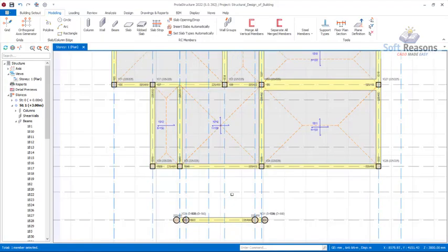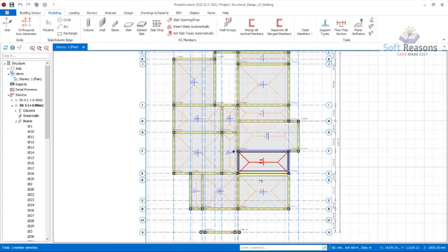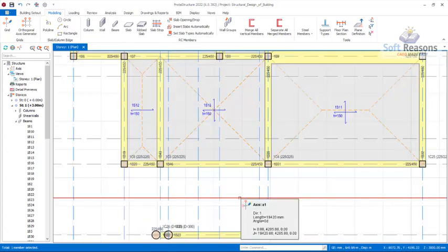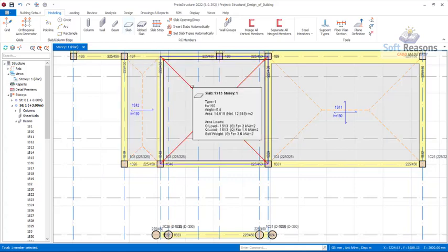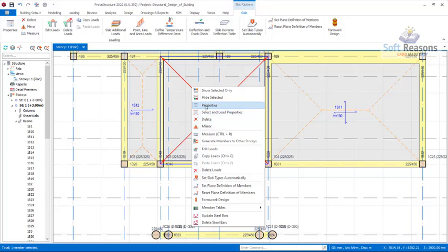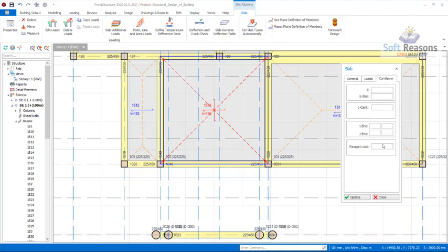So we proceed. Having placed the reinforced concrete slab successfully for this cantilever slab, because this is the first floor, you can see at height 3 meters. So we need to place a cantilever slab. You can use the property of this slab, then come over to the provisions and change it to slab type 12. After which you can see these cantilever options pop up in this slab dialog. So come over to this provisions.